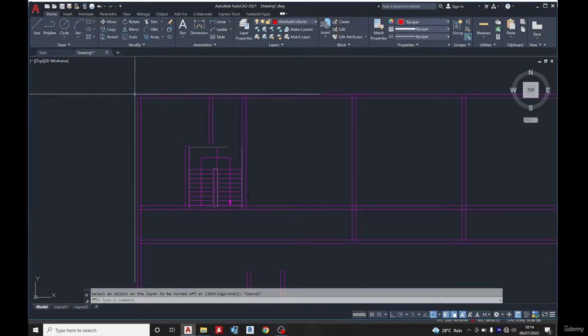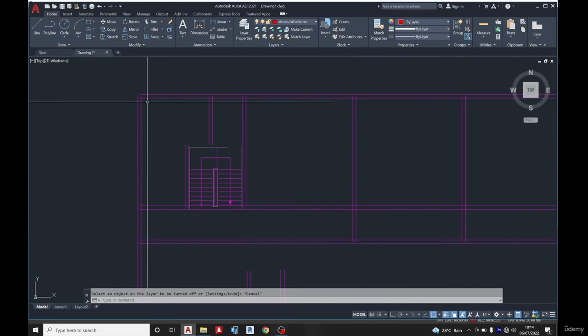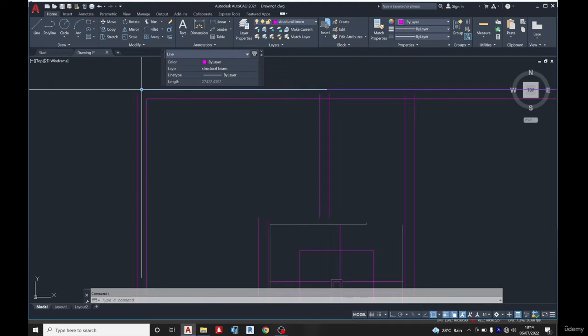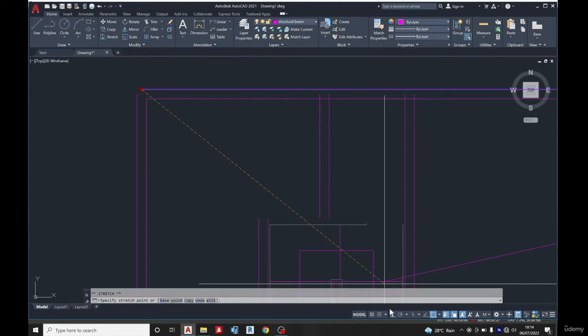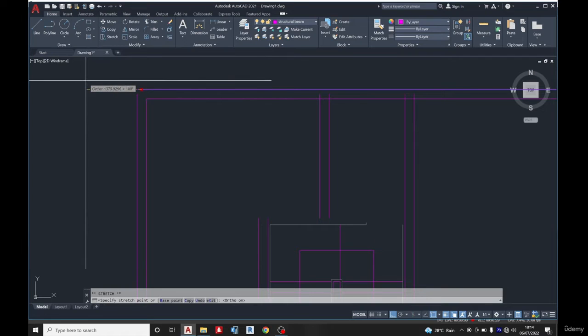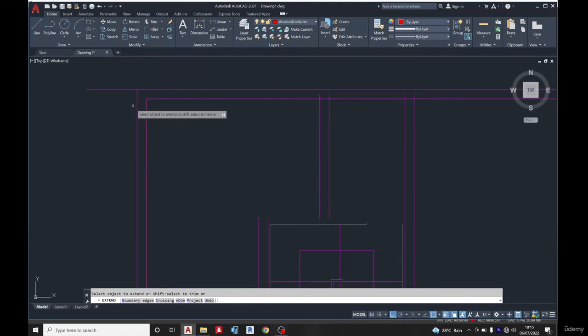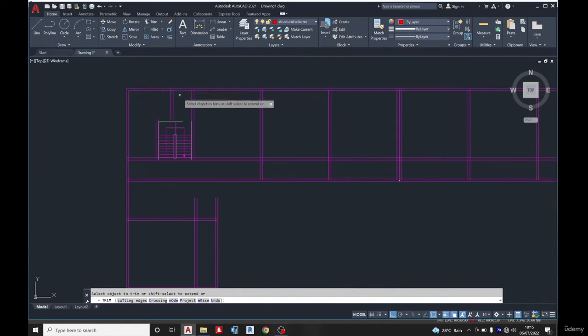So I wish to chamfer, but I can't chamfer because the place is not coplanar. So I'm going to trim, which is the trim command. Select this, trim, also trim. Then I can decide to stretch this one out. Turn on your auto or press F8 on your system, then extend. Okay, so extend it, trim this, and we'll go about this.